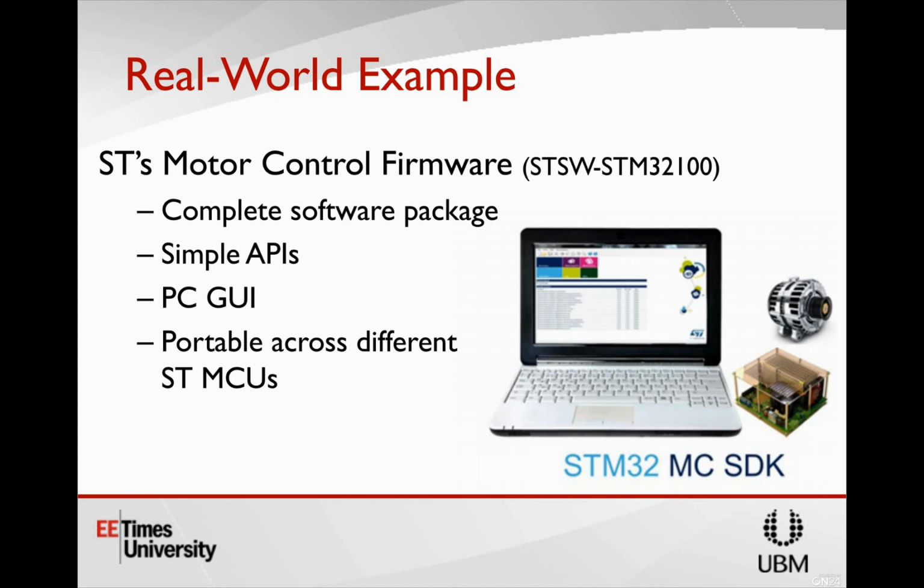Okay, here's one from Jose. About the current sensing hardware, I am assuming it is a half-bridge driver. The sense resistor on the low side is a high impedance, 10 kiloohm resistor, and the voltage is what is read by the ADC to determine current flow. So that's a good question.